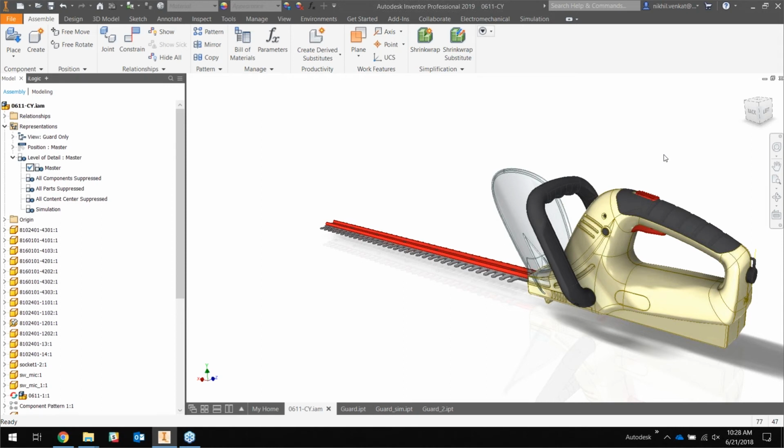Okay. And again, that's regardless of how it's modeled, whether it's an assembly or one composite part, you're still going to see those stress peaks. So maybe consider a nonlinear analysis and see what that does, because the behavior at those stress concentration regions is definitely not linear.